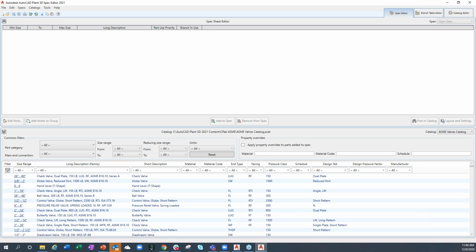So, kind of to follow up on that previous question, they were asking if you use Plant Modify Shared Content folder to place your shared folder on a network path, will your custom block support files still work as intended? Yeah, they should. They might be a little slower just because you are accessing across your network, but it's not going to be that noticeable unless you've got a huge content library with a lot of blocks. It's just kind of like Design Center in AutoCAD. It depends on the speed of it being able to generate all the images for your previews inside of the